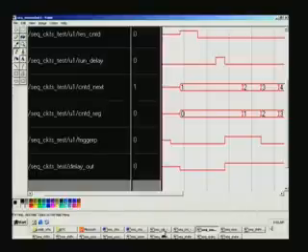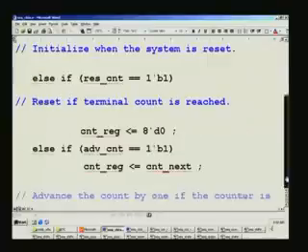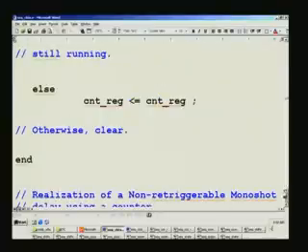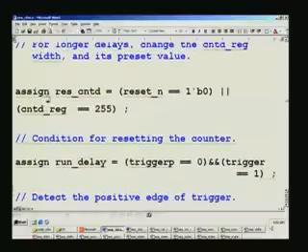So, if you look at the code for this, here we have combined two resets into one statement, that is power on reset here and also counter D being equal to 255, and when any of this happens, this is an OR here, so this will go high.